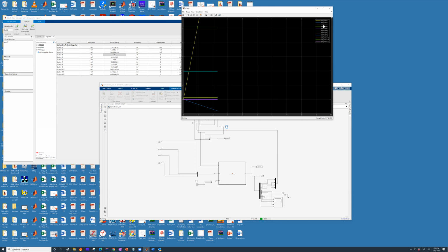This is H. So I really don't care about these three things because it doesn't matter. It needs to be in the level flight. However, if you look at integrator 4, this is my forward speed of 10. It is dot on 10. Integrator 5, note it's almost 0. So you will notice integrator 5 is 0. And all other derivatives are staying 0.